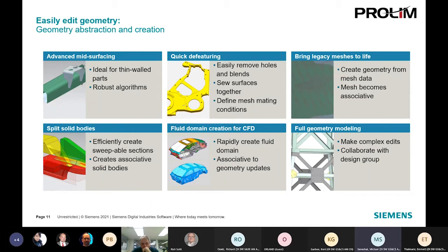So one of those tasks for the designer up front is, when you're doing simulation, it's not just taking the 3D solid, putting a 3D mesh on it and solving it. That's not always the case, right? A lot of tools out there will force you down that path, right? Just put a 3D mesh on it and get some results. But with our solution, we provide a lot of tools to help abstract, or what we call idealize, the geometry.